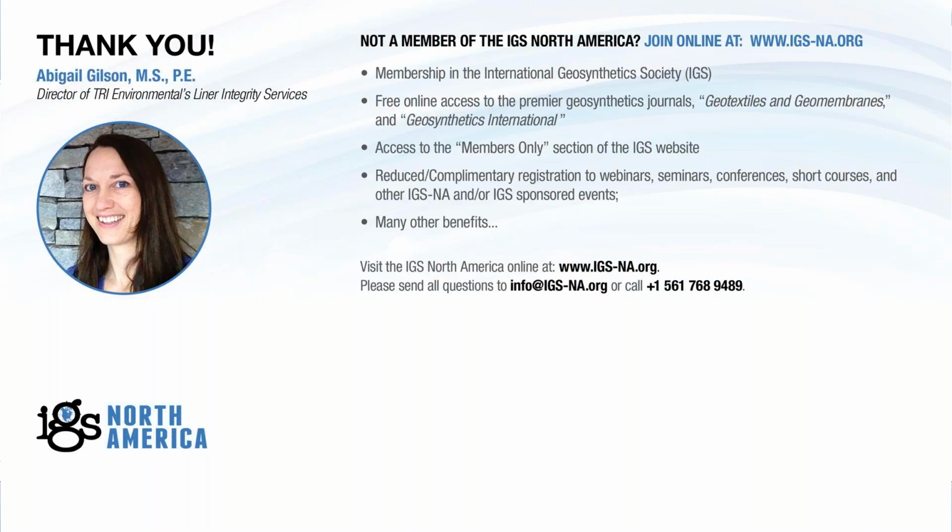Yeah, so you definitely have to have a connection to under the liner. I'm not sure if I understand the first part, something about relative conductivity. I can tell you that you should really read this paper that I wrote a couple of years ago about the site response current, because it's really illustrative. If you have too high of a site response current, for example, current just going through the intact geomembrane too much, you won't be able to do the survey.